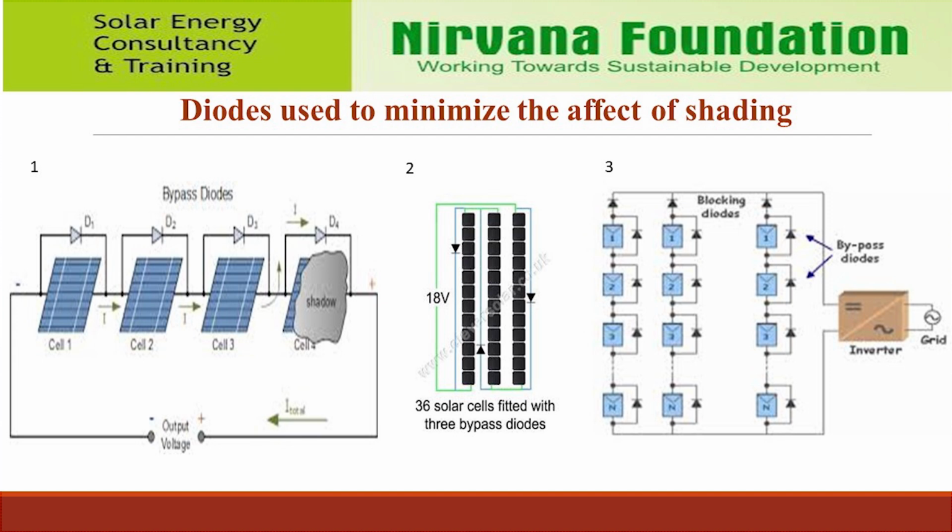Although it would be theoretically ideal to have a bypass diode for each solar cell, for cost reasons a typical solar module will have 3 bypass diodes, effectively grouping the cells into 3 series cell strings shown in Figure 2. For instance, a 36-cell module will typically have 1 bypass diode for every 12 cells. A DC optimizer adjusts its output voltage and current to maintain maximum power without compromising the performance of other modules.